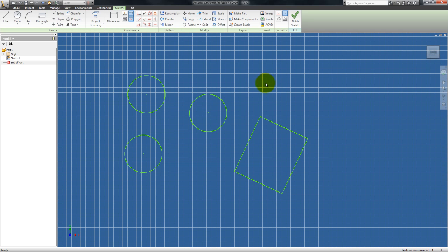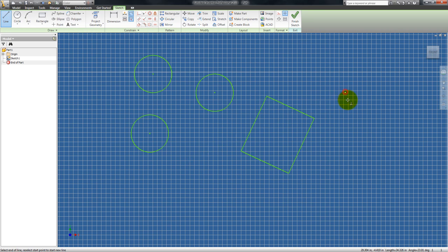Trim, extend, and split. So these are useful for lines. I'll show you in which way. So if we have a line that goes like this, maybe like that too, we want to trim it. I'll show you what trim does. Trim will cut it between two other lines. So we can trim out this from here to here on this line. So there, it trims it out of the box. Let's trim this guy too. Another example, we could trim out this corner. Basically, if you have two fencing lines, we can trim out the stuff in between.